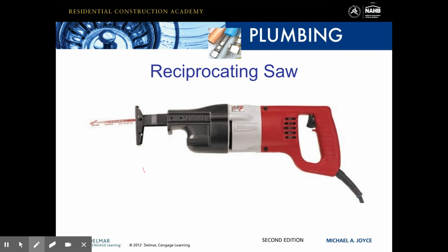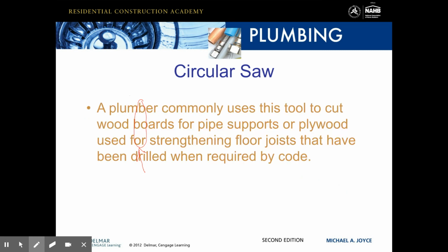And of course, here's the shoe that they're referring to. And this needs to be placed against whatever object that you're cutting. If it doesn't, the whole sawzall is just going to bounce uncontrollably and it can result in injury.